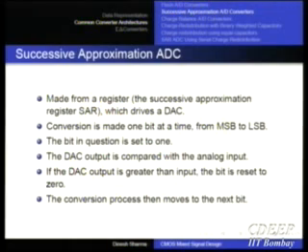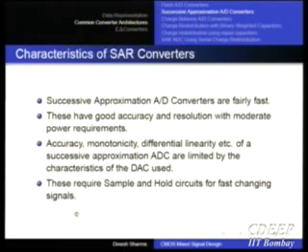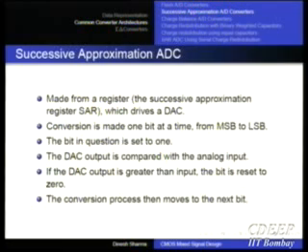And then you find whether the input is higher than this or lower than this. If the input is indeed higher, then you leave it at 1. If it is lower, you clear it and then ask for the next step of resolution and so on. So this part is quite natural to do. Essentially, you are just changing the resolution every step.